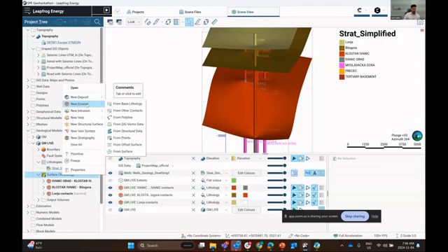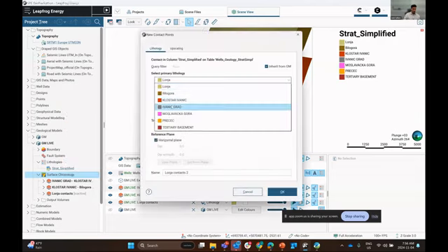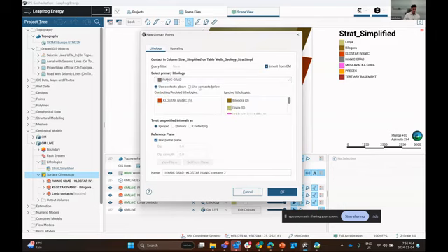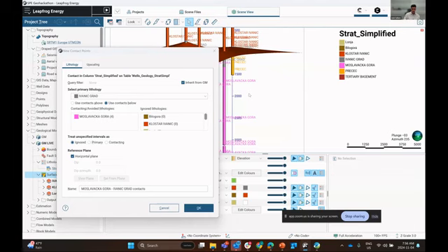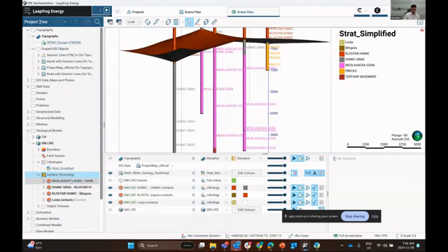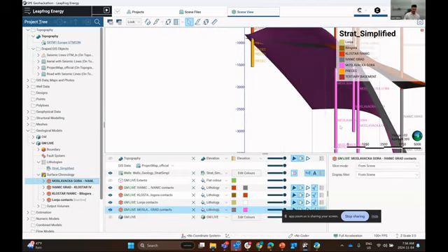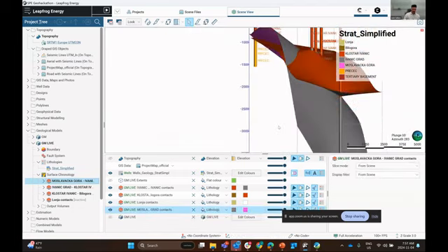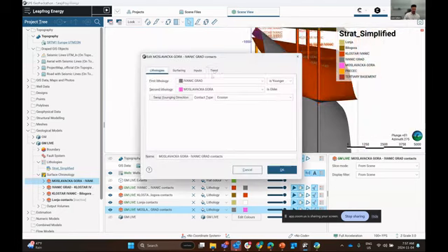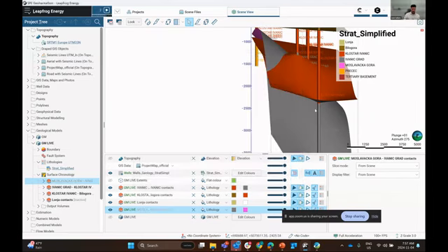I'll right-click new erosion from base lithology. I'll choose the gray unit, use contacts below, and I'm actually going to ignore that orange unit for now. Press OK, drag and drop. Check out the overall trend associated with this unit, double click, and we can flatten this out in the same way that we flattened all of the other units out.